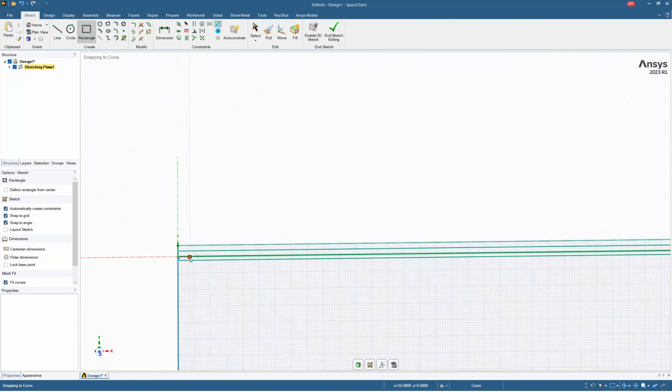Since the functional layer and the support layer will have different properties, and here also there's a functional layer and the current collecting layer, we need to have different geometric entities. Now the mesh is also included, and the mesh thicknesses given are 300 micron and 500 micron, with 500 micron at the anode side.